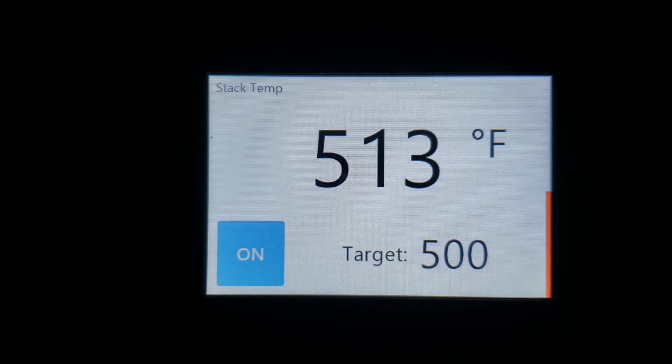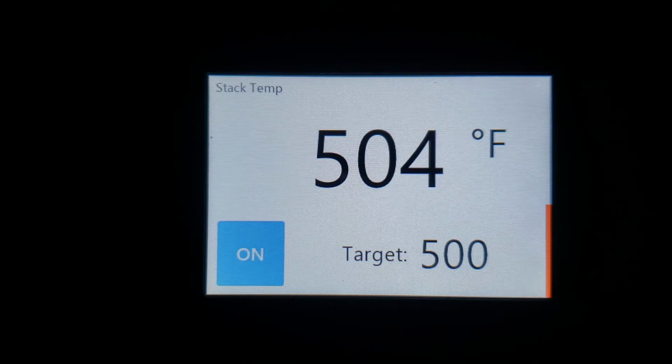The controller is going to be constantly adjusting in order to lock onto that target temperature. We're really just showing you what happens when you go above and below that target, just to show you what's going on inside the system. But if we bring that back down, you'll see that when we get right onto our temperature, that speed is going to pretty much hold steady.